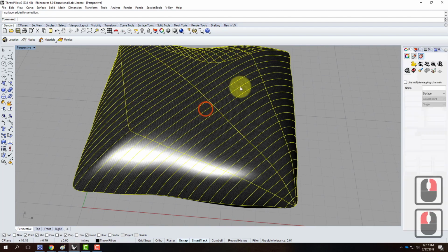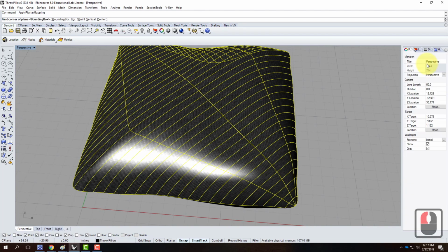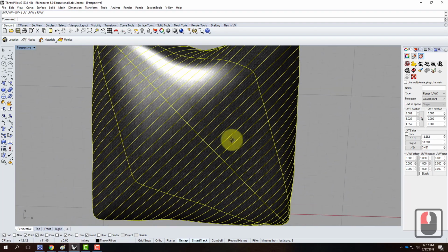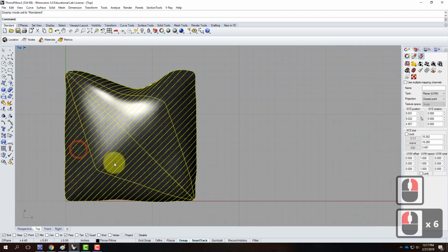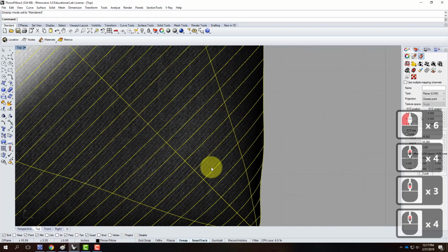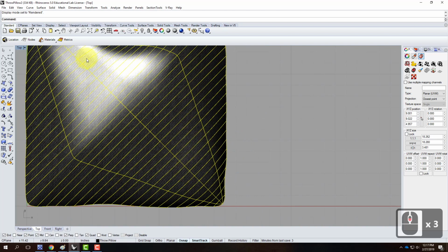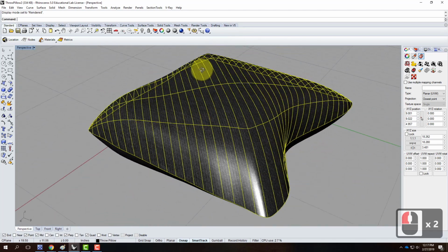If I wanted that to go away, however, I could change the texture mapping to be this other option, this planar mapping. What this does is applies the material straight down from above. So we'll go ahead and say bounding box. We'll say world. I'll go UVW. And it's now applying it straight down on my object. So if I were to look at this in, say, the top view, you might be able to see it a little bit rendered. All the fabric is exactly perfect, regardless of the stretching. There's no swirls. It's just straight. So that might be a look that you're after, depending on what the material is, as to whether you want the pattern to turn or to not turn. It's just a matter of how you apply the texture mapping.